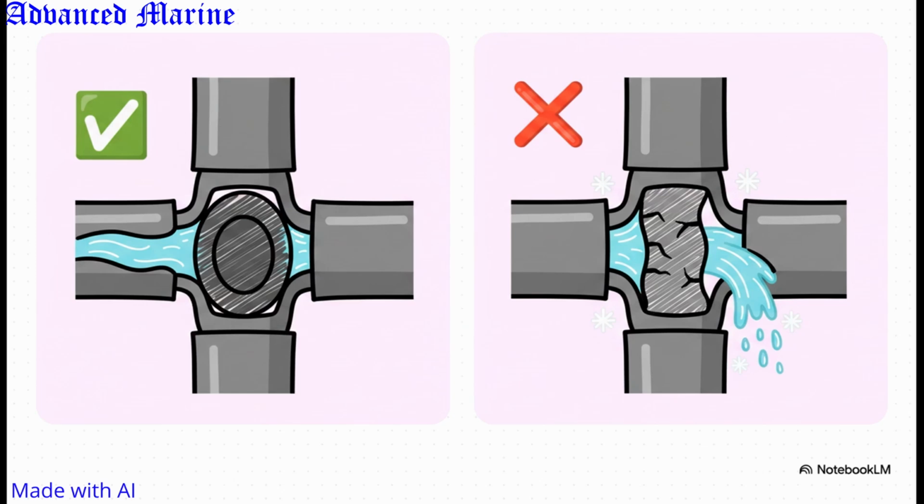But seriously, look at the do not use list. Contact with natural rubber, nitrile, polyurethane, or Viton is strictly a no-go, especially at low temperatures. If you try to use natural rubber or polyurethane, the cold ammonia will completely destroy the structural integrity of the seal, and that leads directly to a catastrophic leak.